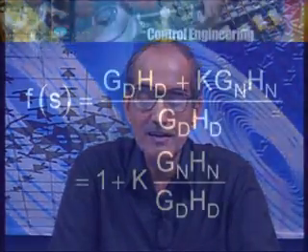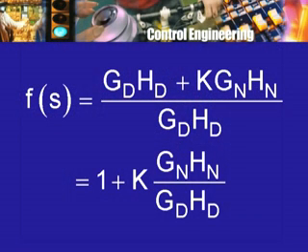What about the denominator GDHD? Well, the transfer function GS is known to us, so if its denominator can be factorized, and we will assume that it can be factorized because these are the poles of G and these are the poles of H. So, for the denominator polynomial, we know the location of its roots, it is the numerator of which we do not know the roots.